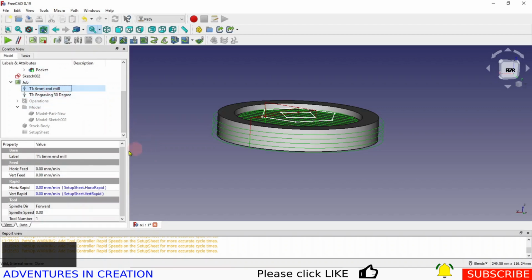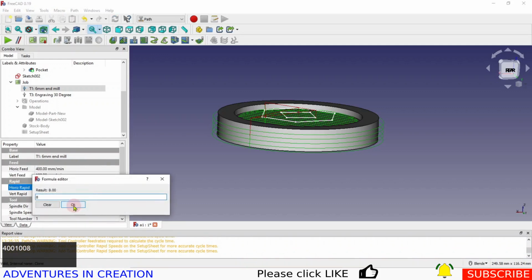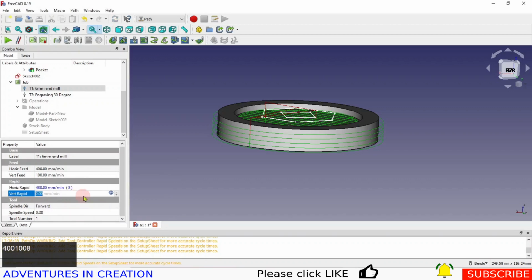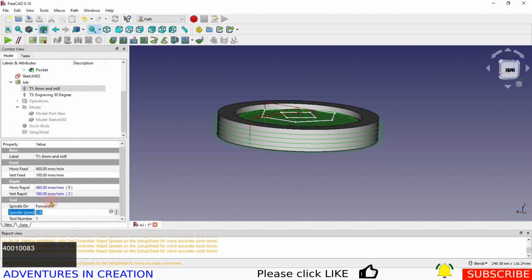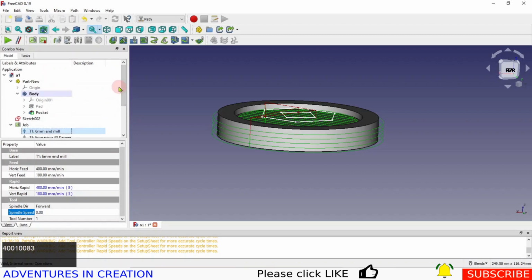So the same thing on the 6 mil. For the horizontal, for the actual cutting, I want to go at 400. For my vertical, I don't mind going at 100 for that guy. This guy, I'm going to go in and do my 8. And for this guy, I'm going to go in and do my 3. And there you see the numbers look reasonable. So if you don't set those up, you can't get timings for your job. So it won't tell you how long things are going to take for your operations.